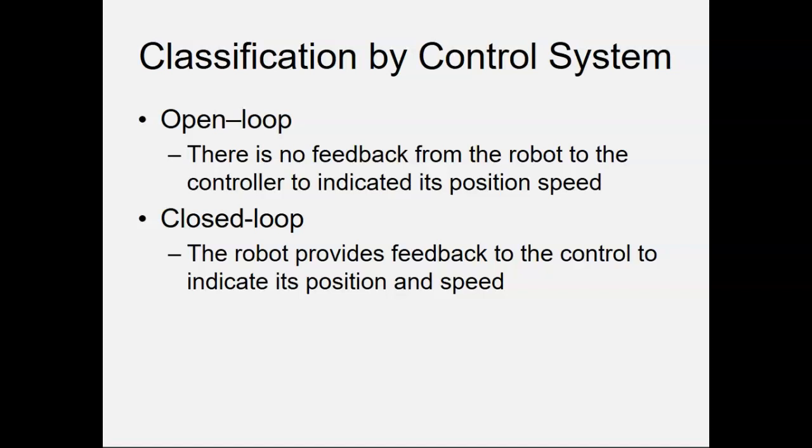If we weren't having class over there, I'd show you all on the line. But there's what's called a gantry robot. And what this gantry robot does is it moves along this one slide. It can move left to right, and it moves up and down where it can grasp and move different things in manufacturing. We don't classify it as high intelligence because it just runs the motor until it hits the stop.